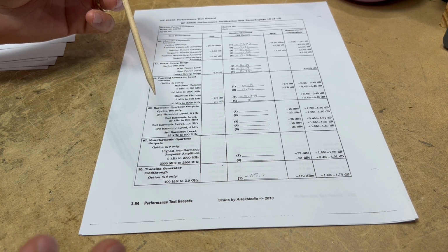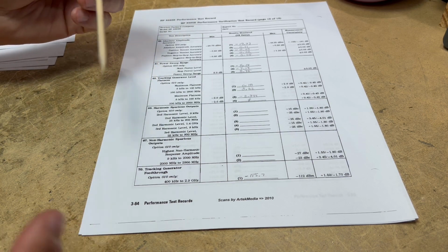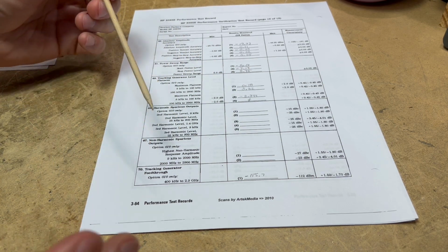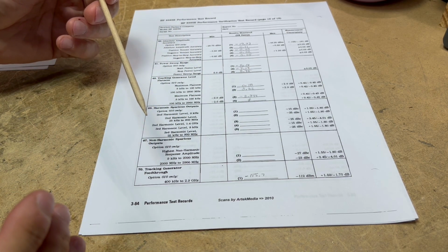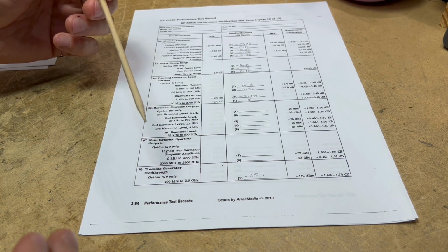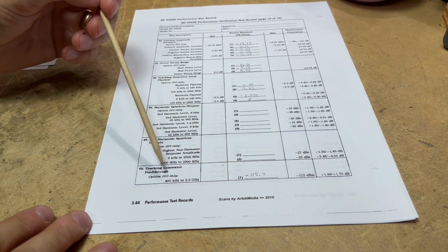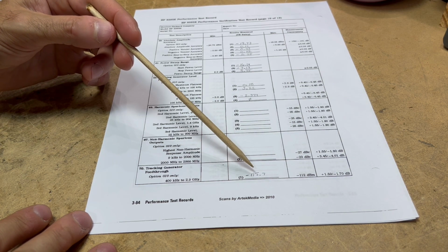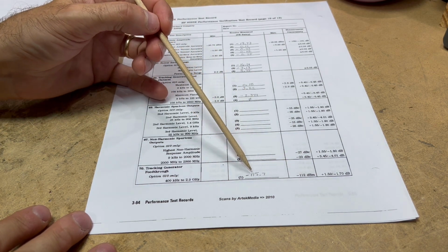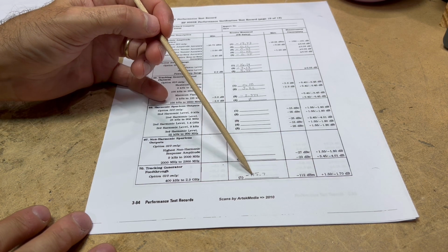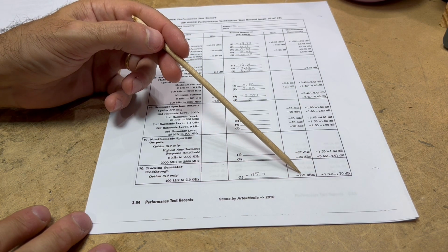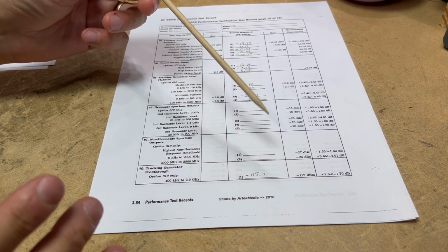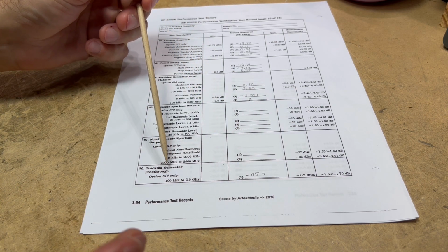The coax that I did use was too leaky, and it was allowing some of that tracking generator signal to leak out in the instrument. When I replaced the coax with rigid coax, that cleared up the feed through, and I got it back into allowable spec. The highest level was minus 115.7, with the max allowed being minus 112 dBm. So changing out the coax on that modification resolved the feed through problem.